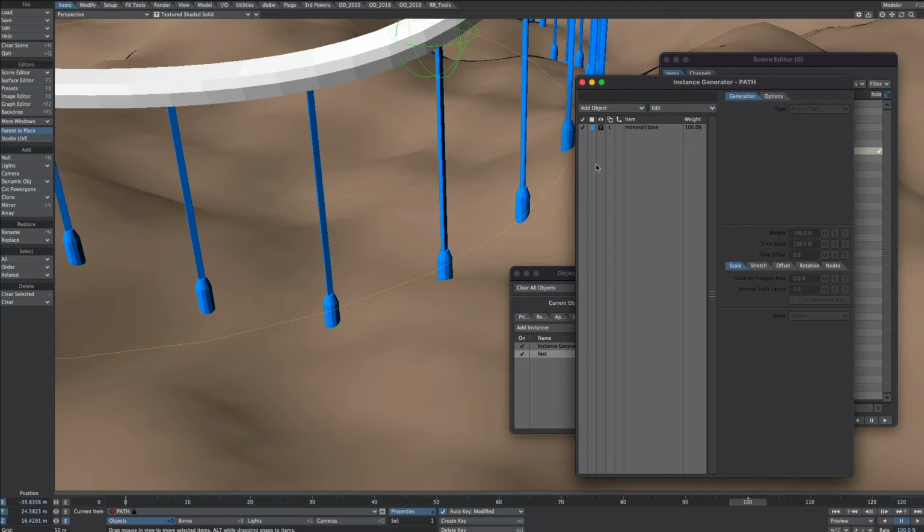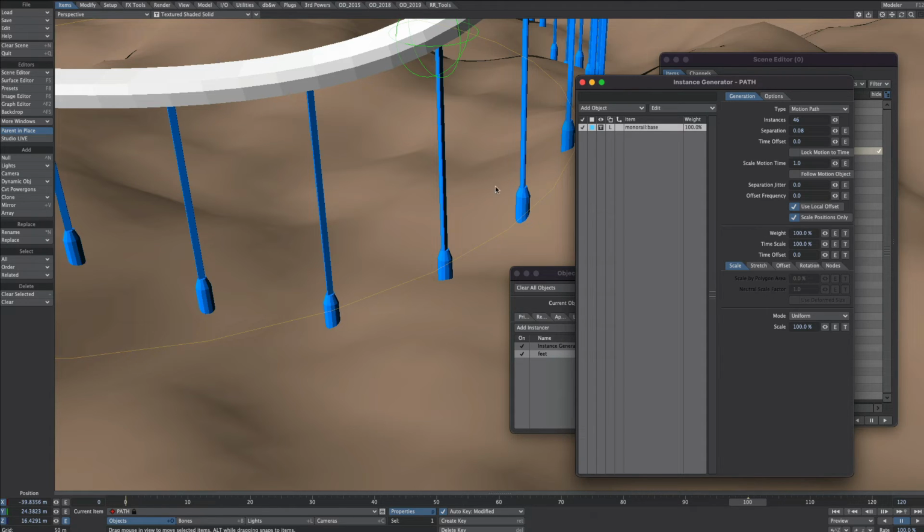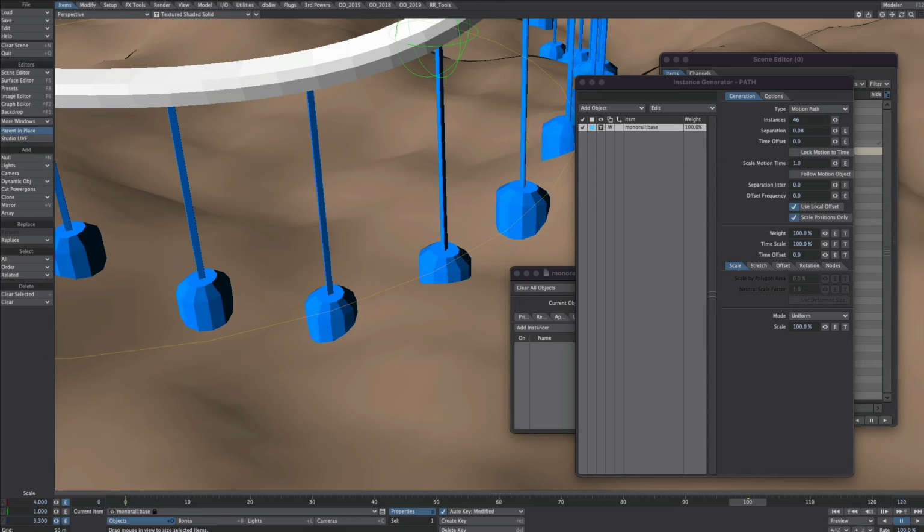It's also worth mentioning for these feet, if we want those a bit fatter, rather than going to modeler, we could select world coordinates, select our feet, or base as they're called, and just scale along the X and Z.